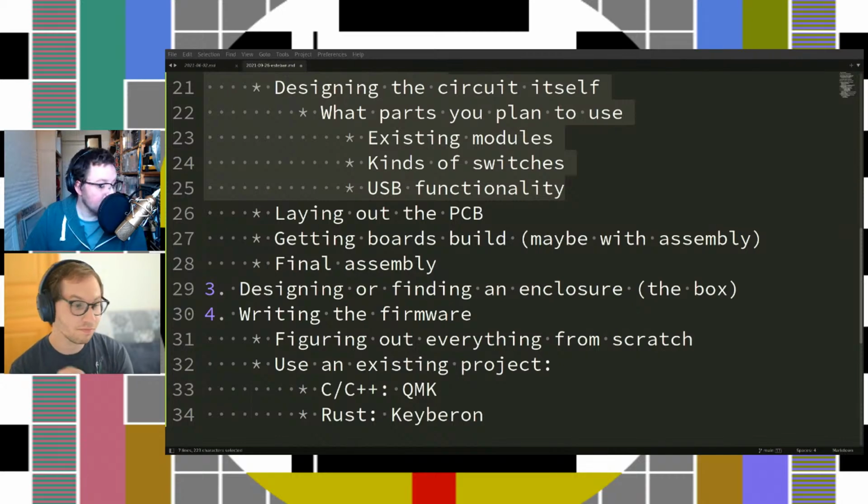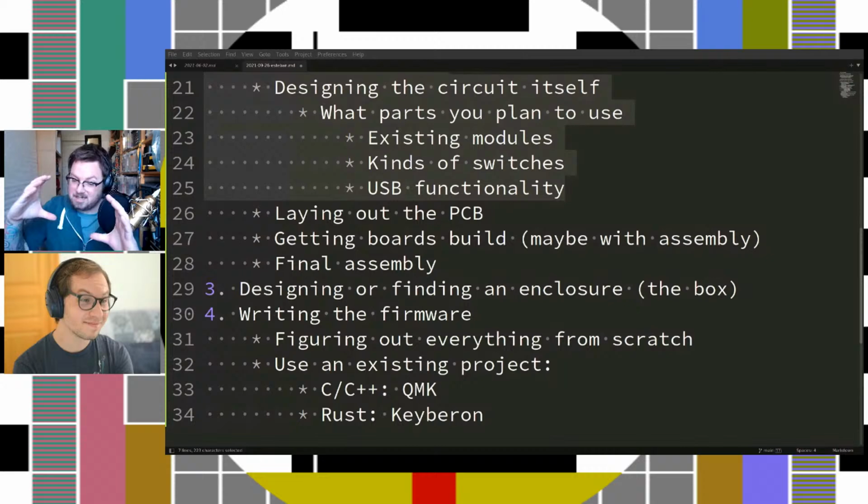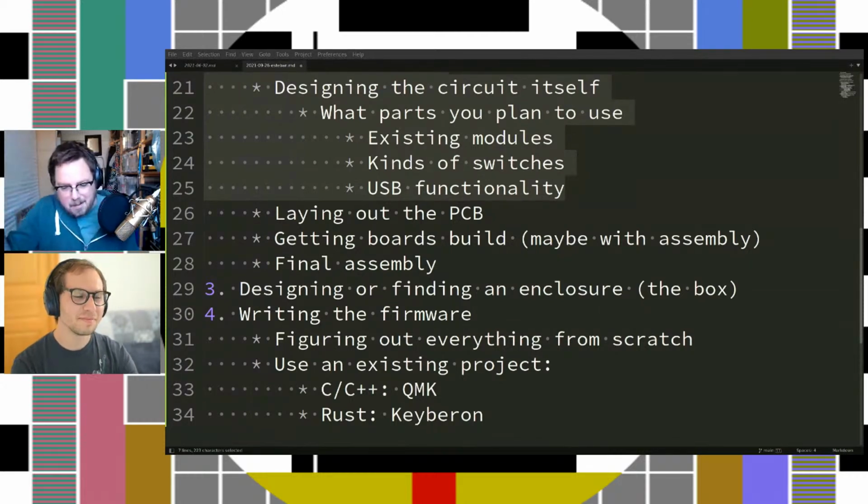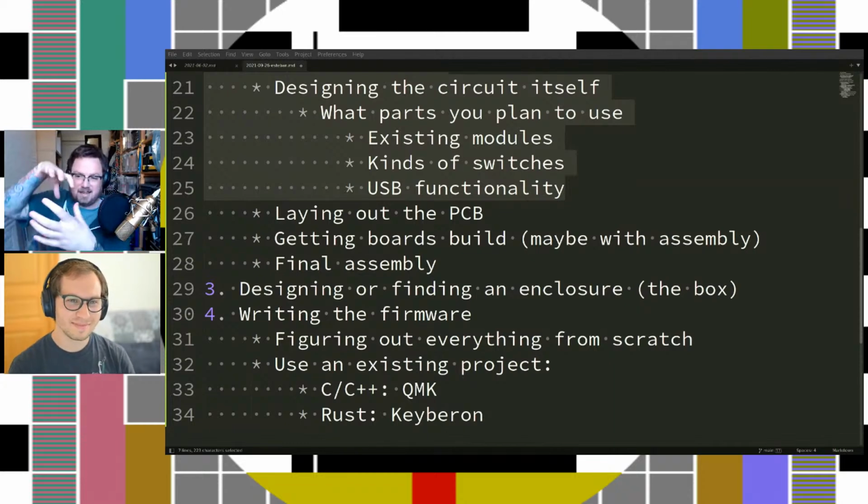Yeah. There's nothing wrong with, like you said, if it's stupid and it works, it isn't stupid. And I'll admit I've shipped a lot of projects where customers were like, we want a demo in 6 weeks, and I'm like, is it okay if the box is this big? And they're like, yeah. And I'm like, cool. So this is a Raspberry Pi with a USB 4G dongle with a flash drive, and then one little custom PCB that does protocol translation from the Raspberry Pi to some proprietary customer bus. And I'm like, as long as you're cool with the whole thing being ugly and the size of a brick, I can do it.